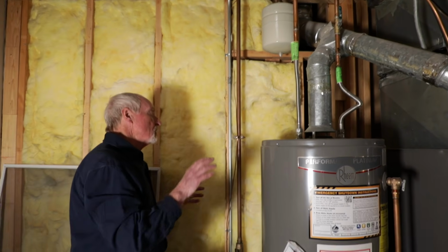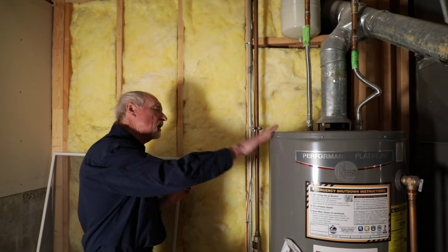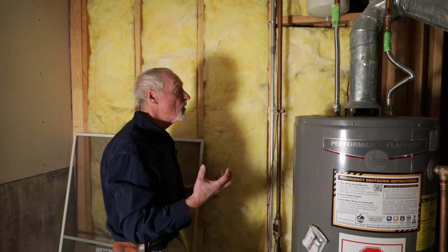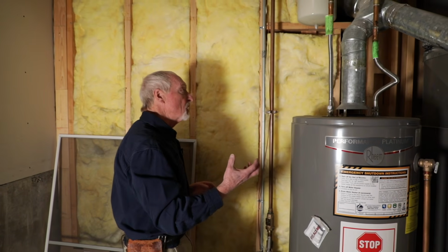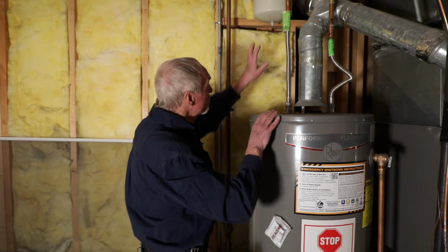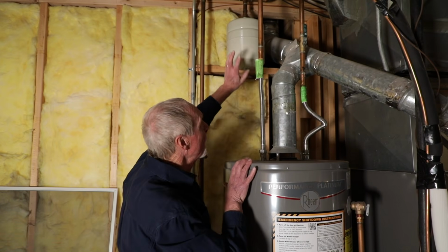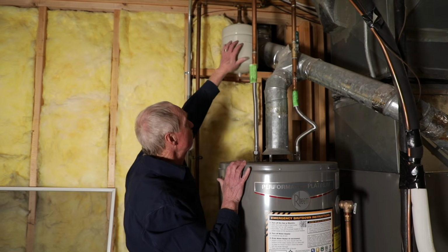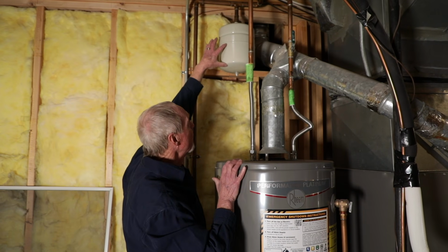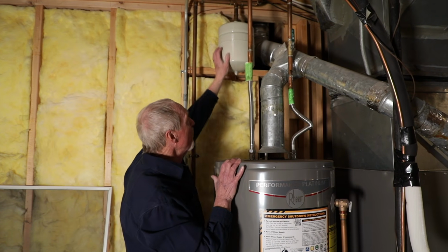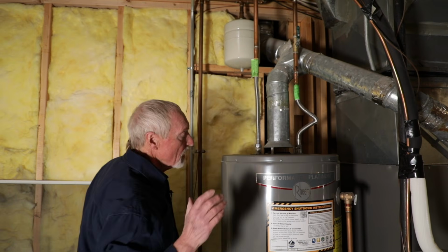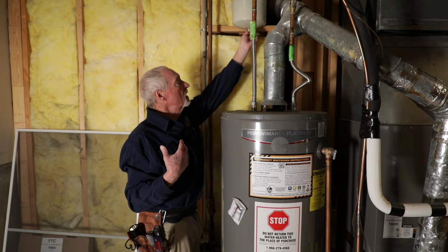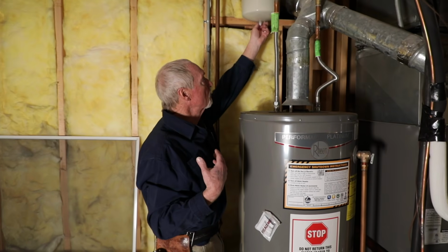The reason for this is when the water heater is heating water, it can dramatically increase the water pressure in the house, and by a lot in some cases. And so we want to absorb that excess pressure by some way, and in this case using an expansion tank, which has a rubber diaphragm in it. We have air in the bottom of it, and then we'll have water in the top of it. You are not required to check these. I usually do, because they have a very high failure rate.